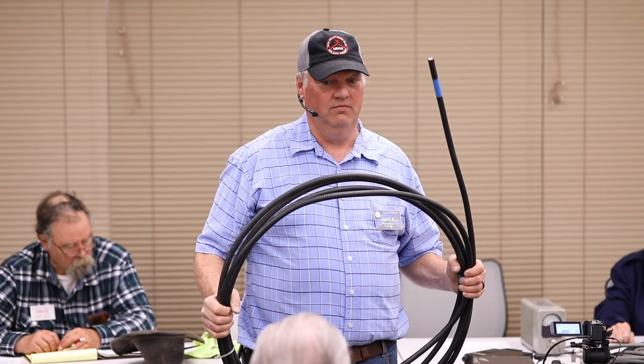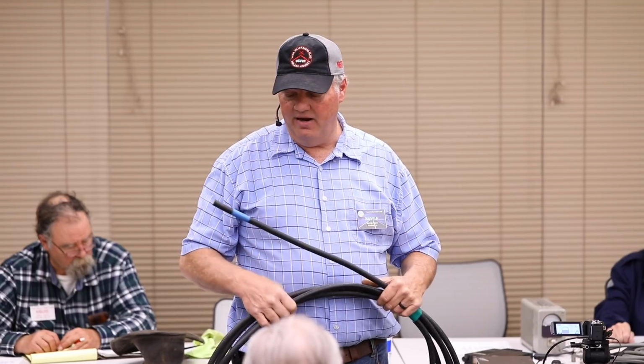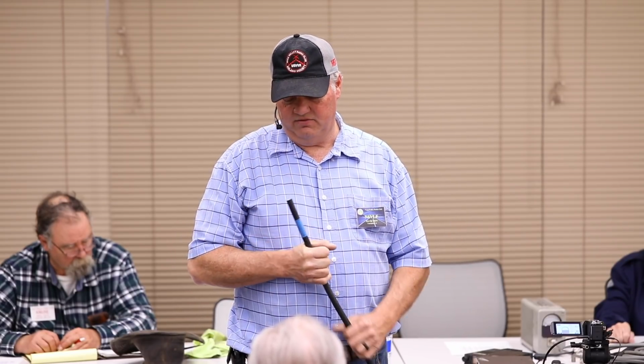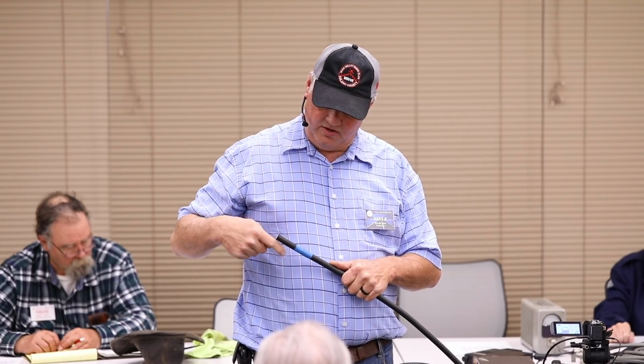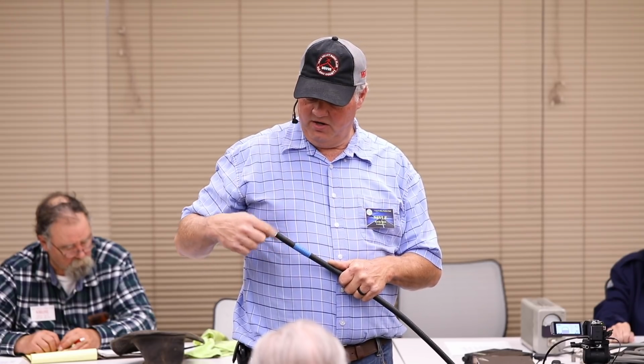Unless you go off the deep end and start buying stuff like this. Most of us don't. This is a scrap that a cell phone company guy gave me. And I think it's, don't quote me, but I think it's 5/8. Does that look like 5/8 to you guys? Yep, this is 5/8 hardline. After we get done, you can take your knife and pull this out. You can see the corrugated copper, which is a shield. You can cut the insulation, the dielectric, off, and look at that center conductor that's bigger than a number 10 wire, I think. Maybe an 8 or 9 or something.